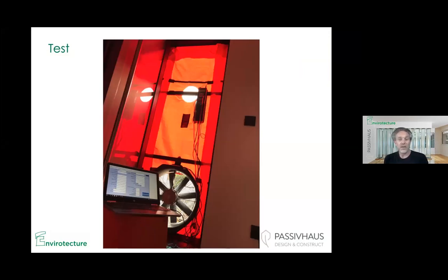Once it's built, there is a blower door test. This is what these things look like. It's basically a canvas thing stuck in a door, with a big fan at the bottom, hooked up to a computer. All it really does is you tell the computer how big the building is in terms of its volume and its surface area. You then set the fan running.